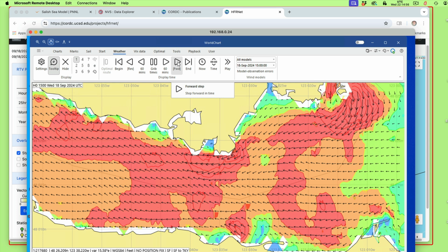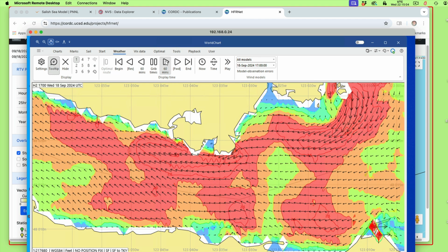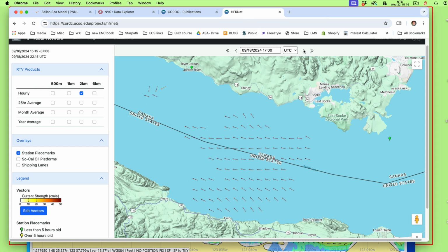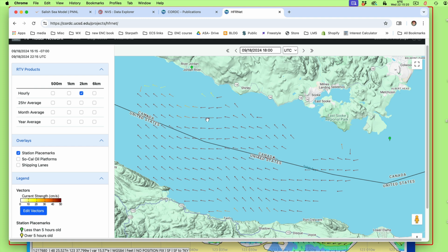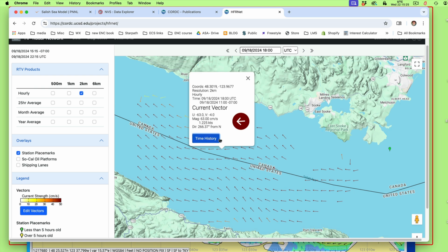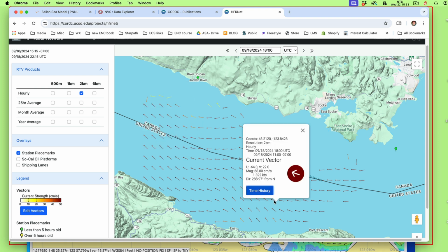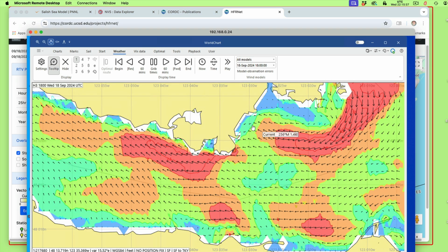And then what we could do is step through, but the directions are all about right, and then you can step through this and look at where it's beginning to turn around. What is this now? 1800, and we go up to these measurements here, 1800, and you're getting a little more structure in the flow, and it's getting ready to start turning around. That's 1.2 knots. Now this is starting to turn up here, 1.4 knots. What do we have over here? 1.3 knots. And this model has this turned up over here, 1.7, 1.8. Still, the model's a little bit stronger, but you do see exactly when it's going to turn around over this great huge basin, not just 1 or 2 stations.